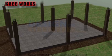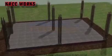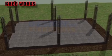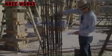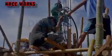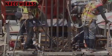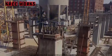Column concreting. After the concreting of footing is complete, immediately in a day or two starters for columns should be casted with proper alignment. Columns are very important members in RCC design. Wrong placing of column may affect the overall behavior of structure. Concreting of RCC columns should start from the center of vertical bars and go towards the ends.